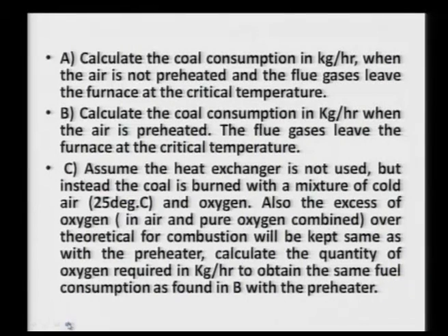76% nitrogen. You have to first calculate the coal consumption in kilogram per hour when the air is not preheated and the flue gases leave the furnace at the critical temperature. So, that critical temperature is also the exit temperature of the flue gas, that is the assumption that you are making in this particular problem.